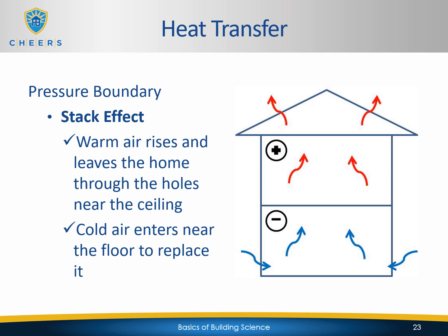Cold air enters the bottom of the building, and we're going to have negative pressure there. It rises, it pushes up, and because the air is being pushed up to the top, you're going to have more positive pressure toward the top of the building. That air is going to be pushed out through exfiltration points somewhere at the top of the building. And that's an example of stack effect.